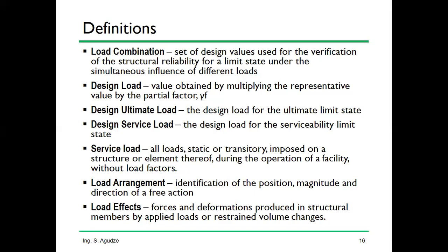And then we have something we call design load. Okay. The actual loads have to be converted to design load by considering some factor of safety, that we call partial factor. So if the design load is under the ultimate limit state, we call it design ultimate load. If it is under the serviceability limit state, we call it design service load.